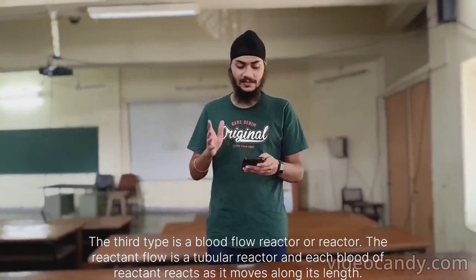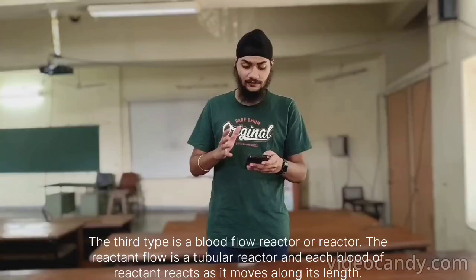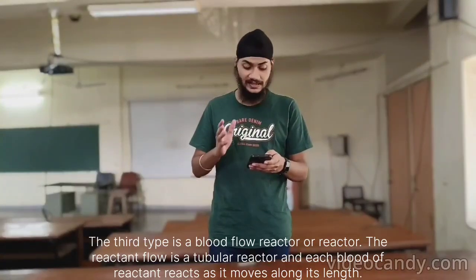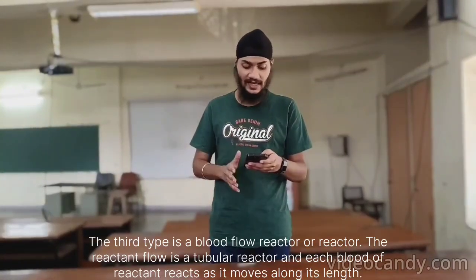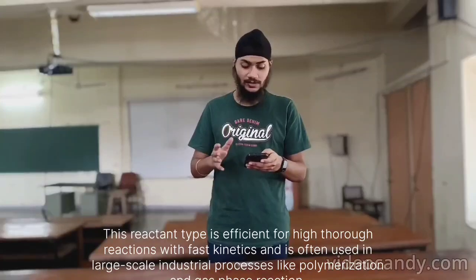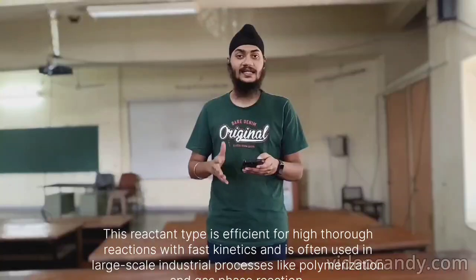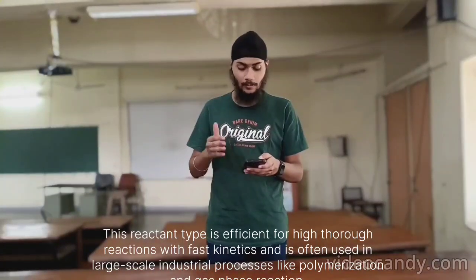The third type is the plug flow reactor, or PFR. The reactants flow through a tubular reactor and each plug of reactant reacts as it moves along its length. This reactor type is efficient for high throughput reactions with fast kinetics and is often used in large-scale industrial processes like polymerization and gas-phase reactions.